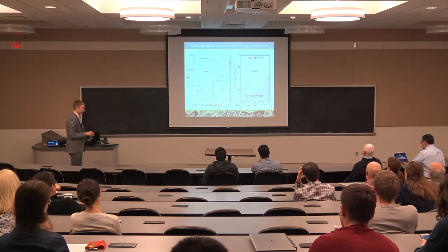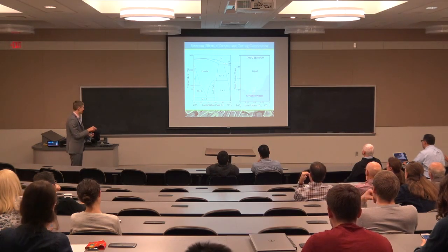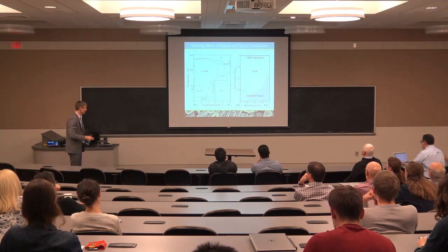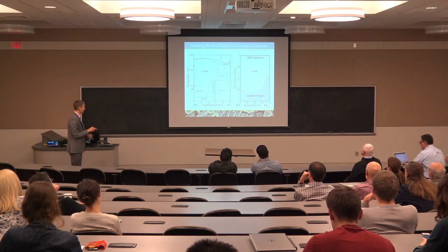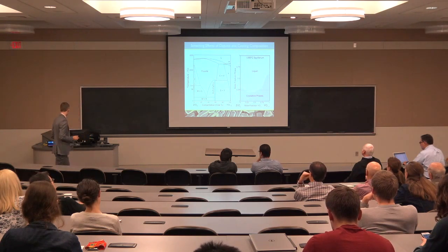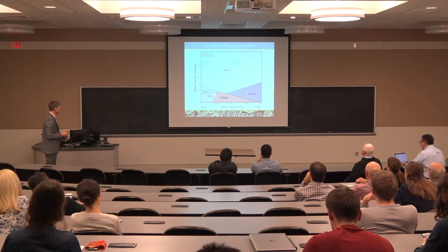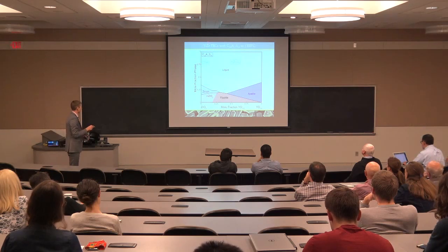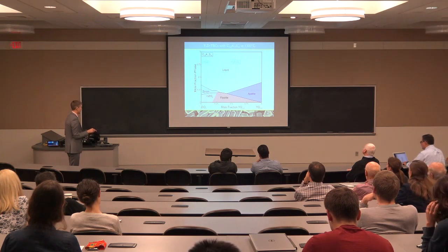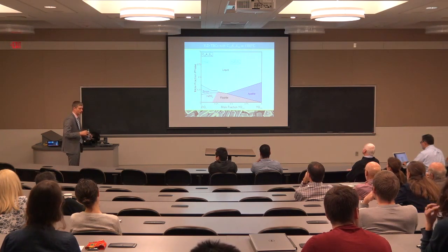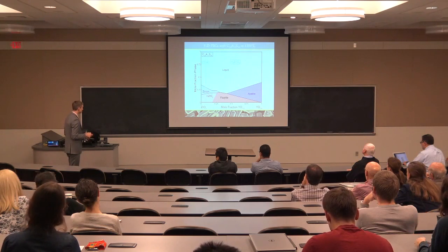In some cases, because of the solubility of the coating in the melt, we might get less back than we put in. And in other cases, we might promote a lot of crystallization. We'd like to pick a coating that has a behavior like this, where we promote a lot of crystallization. So we can look at the behavior of yttrium zirconium TBCs interacting with this somewhat middle-of-the-road melt. And in fact, we find, yes, there's this region in the middle where we don't get much crystallization.